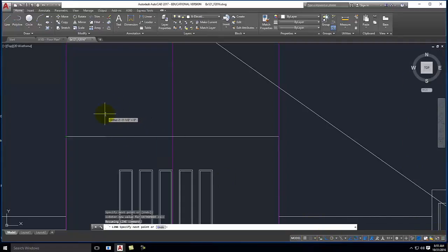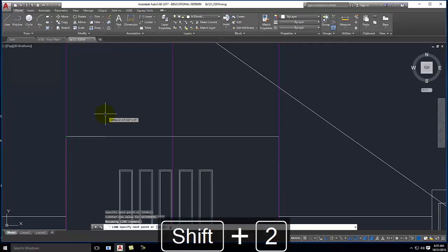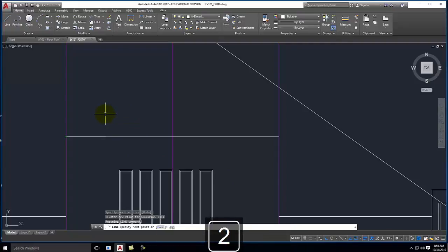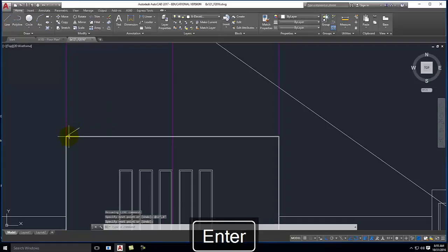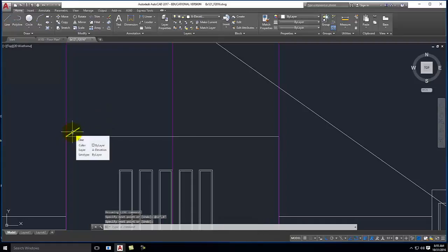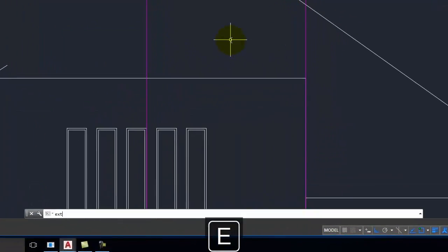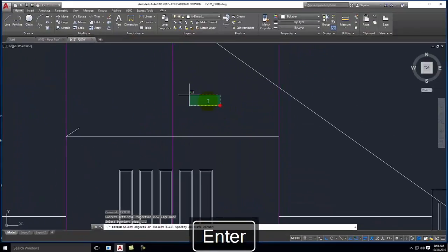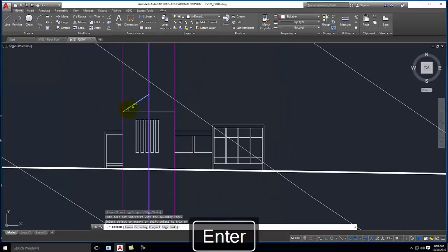And so now we can go ahead and type in @ for the value. We're going to go 12 inches in the run, comma, 8 inches in the rise, and enter. It gives me the slope of 8 and 12, which is really convenient. Okay? So now that I have that slope, we can use extend, which I told you about just a second ago, with that center line. And we'll go up to where we meet the center.